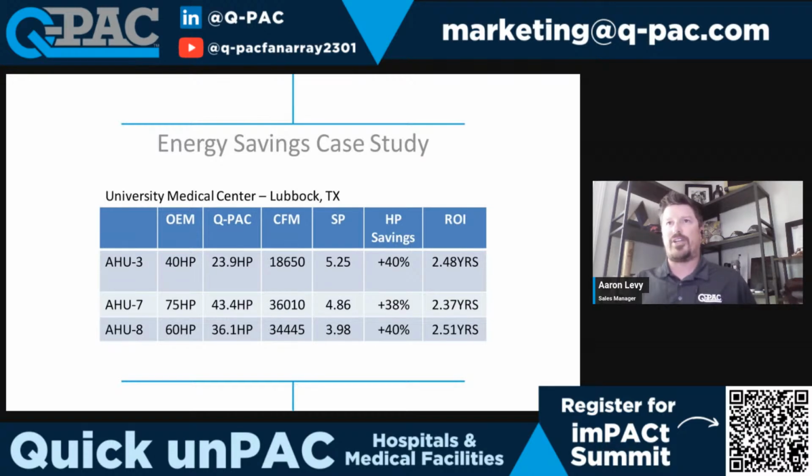Because when we're looking at an AC motor with a VFD, depending on whether it's a belt drive system or even a direct drive system, when we're talking fan efficiency indexes or how to compare like for like, I like to normally talk about total fan efficiency. And total fan efficiency takes away the motor component of it as a whole.